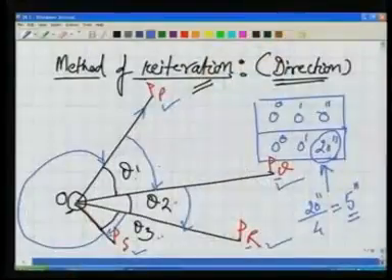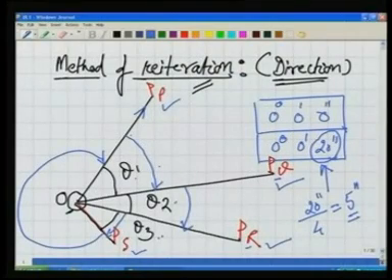Now this observation can be taken right now. For example, let us say we are doing it on face left. You know now the meaning of face left and face right observation. We can do the same thing on the face right also. Right now we are doing it on face left. So we started from P, went to Q, went to R, went to S and closed it. Then we can change the face and repeat the same procedure. So we will have readings or angle values for face left and face right.